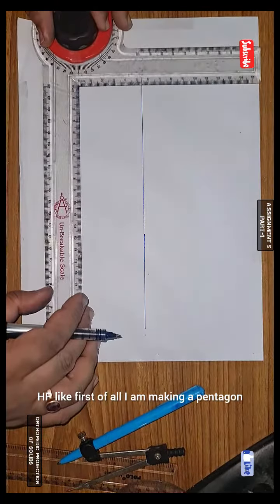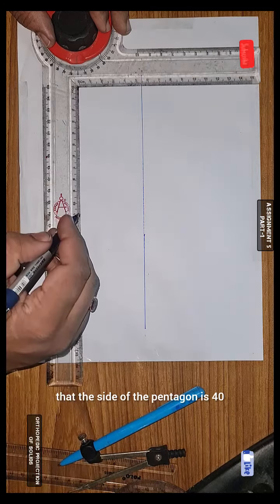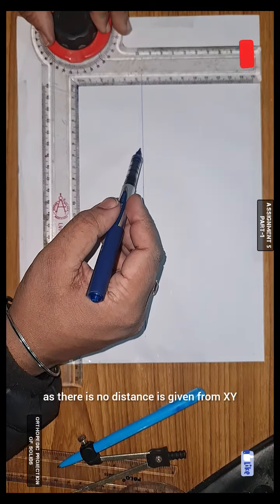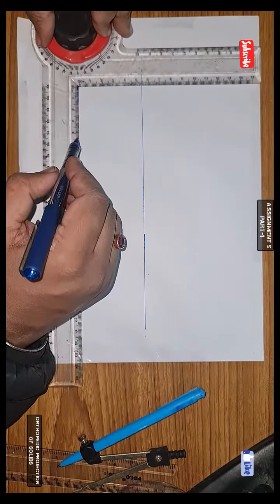Like first of all I am making a pentagon. For pentagon it is saying that the side of the pentagon is 40. As there is no distance given from XY line, you can assume it. If there is some distance, you have to take that.